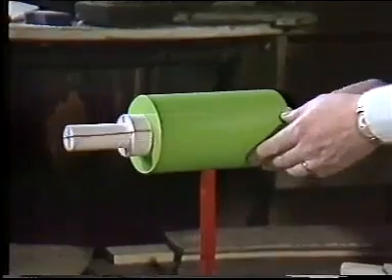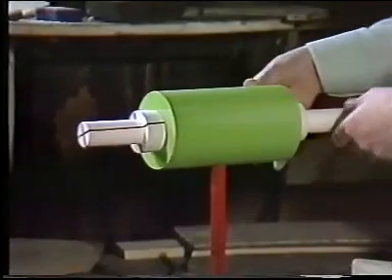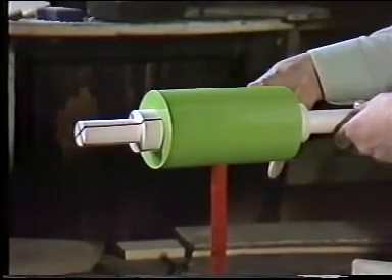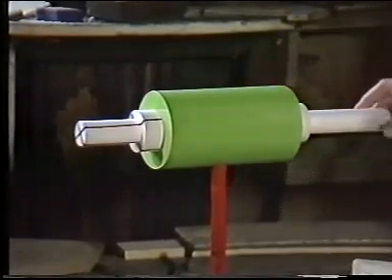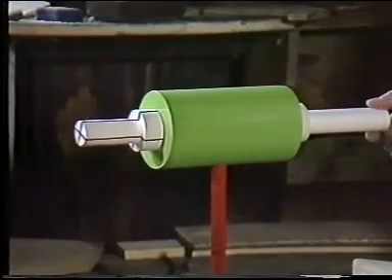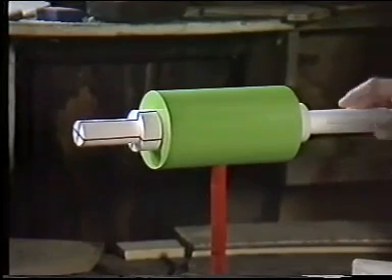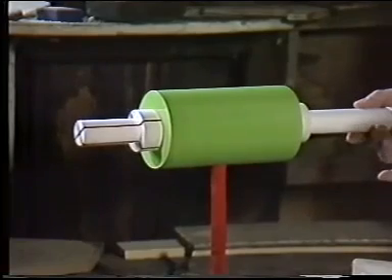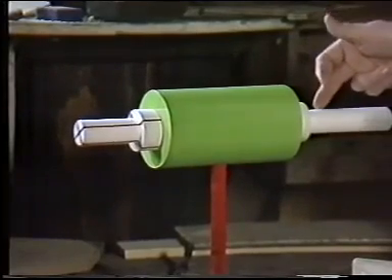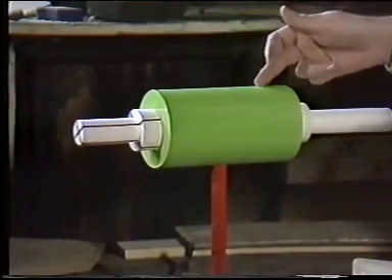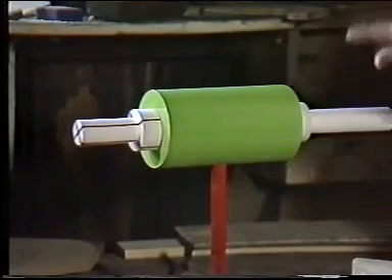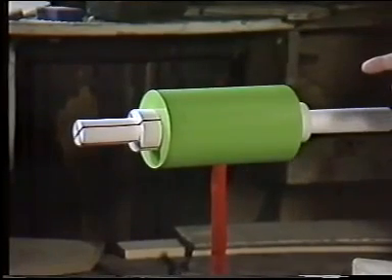Now here I can have a turning motion, but I can't have any sliding at all. And so again, there's only one way I can move one link relative to the other. Only one parameter, the amount that the link has turned, is needed to specify the position of one link relative to the other. And again, therefore, the joint has 1 degree of freedom.